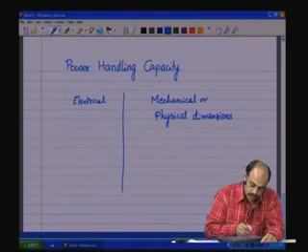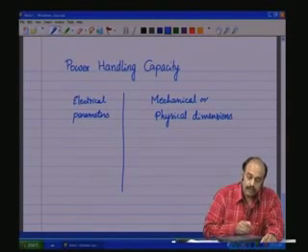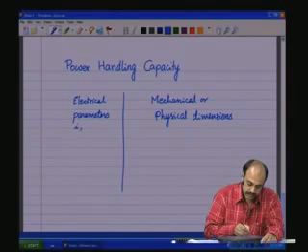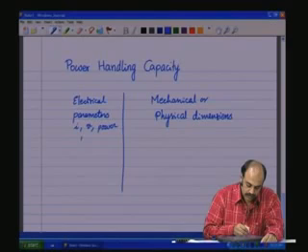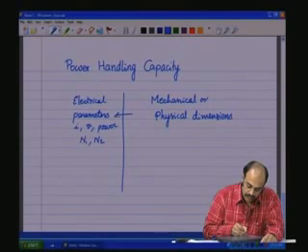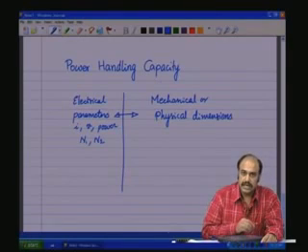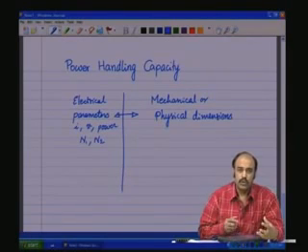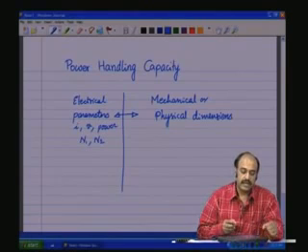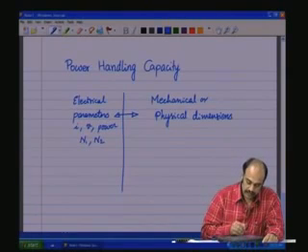You have the electrical parameters in terms of the currents, the voltages, the power, number of turns, N1, N2, so on and so forth. And to that we need to have some kind of a relationship with the physical dimensions of the core with respect to the core sizes, the sizes of the wire gauge and things like that one. So, what is that mapping and how is that done?